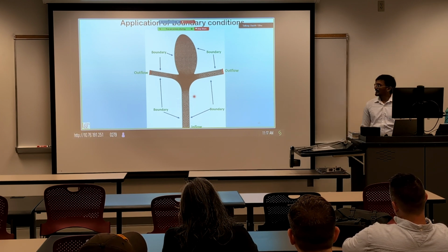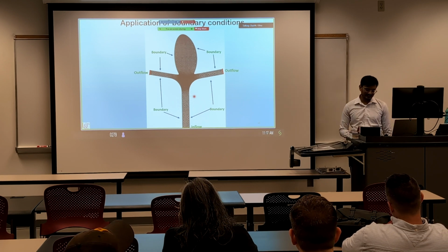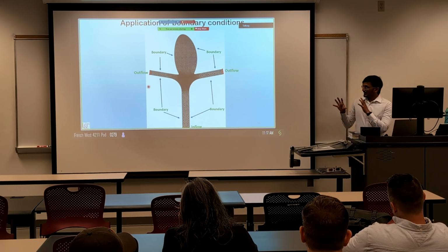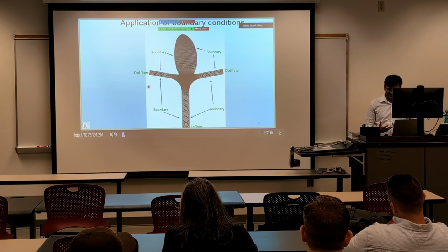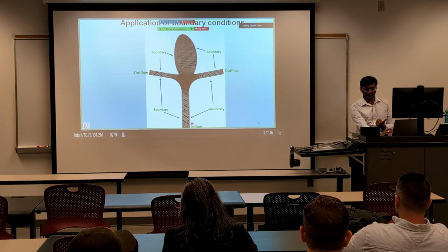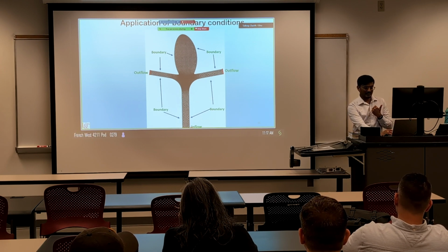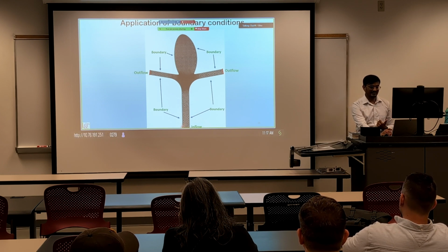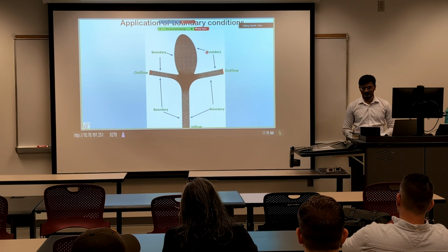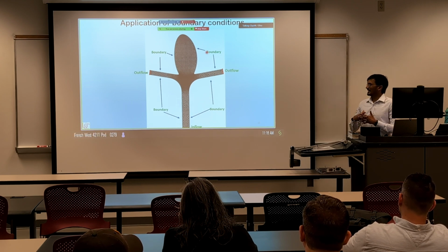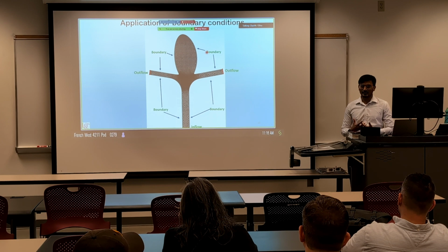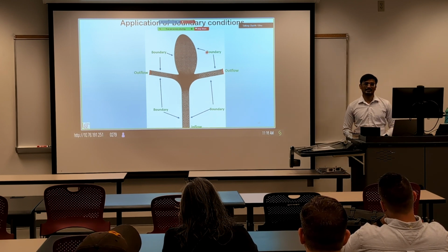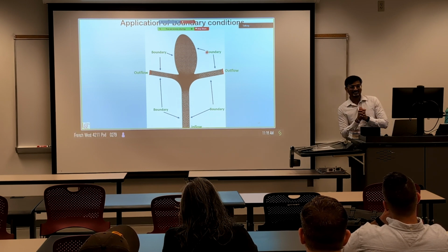Then we have to apply the boundary conditions. What are the conditions we have in these boundaries? Now, the way this code works is, we have to specify the pressure values at the inlets as well as the outlets, and then the no-slip conditions on the wall. That's how this DolphinX module performs the calculation to solve the Navier-Stokes equation. Did I answer your question?